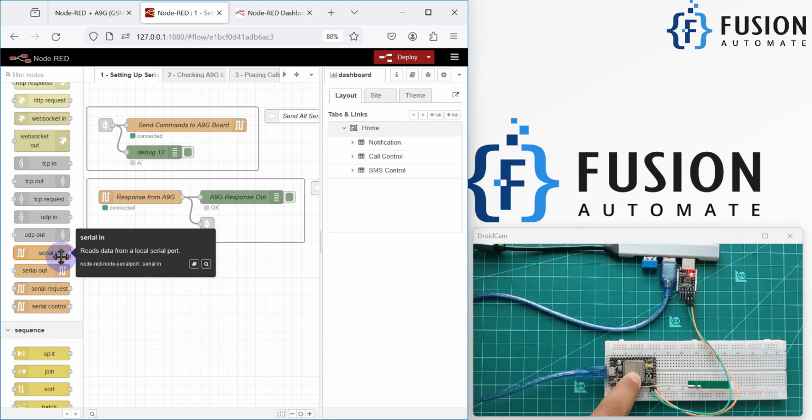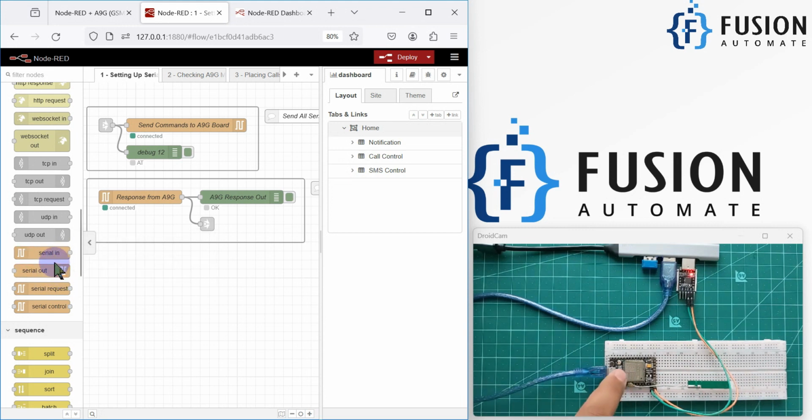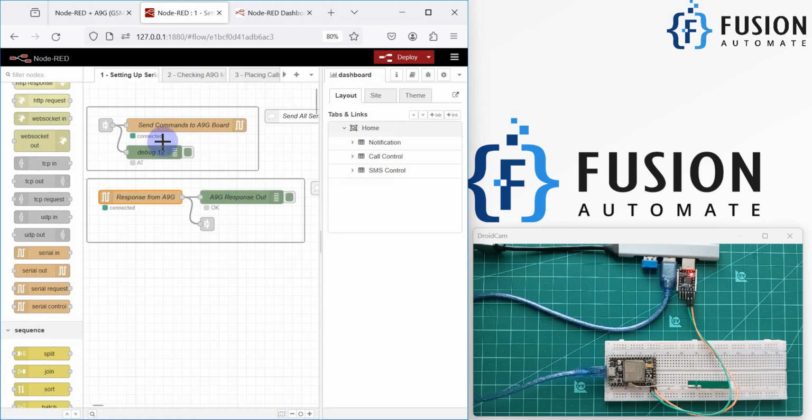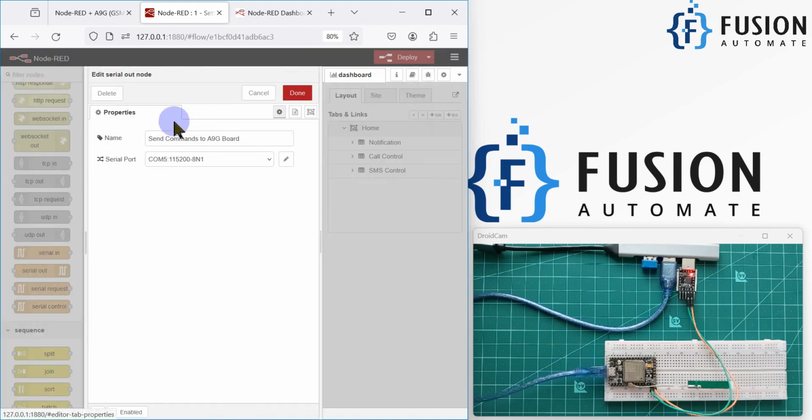The A9G board will send a response to our system via this serial communication. So I can read the data using the serial in node, and whatever data I want to send, whatever AT command or SMS body, I can send using the serial out node. Now here you can see send commands to A9G board and response from A9G board. Response means we are using the serial in node, and to send commands to the A9G board we are going to use the serial out node.